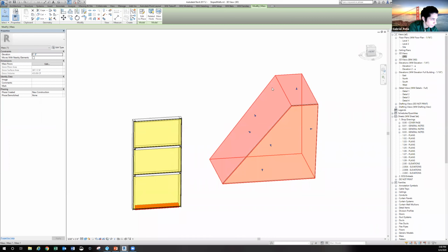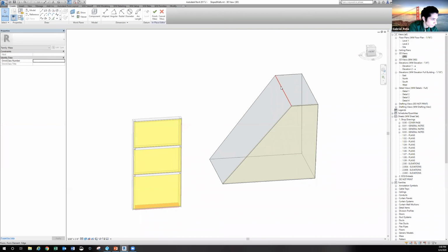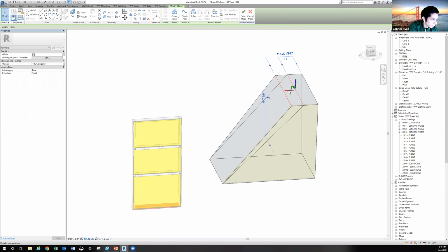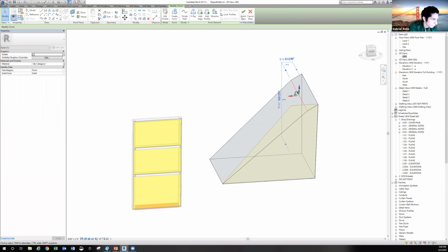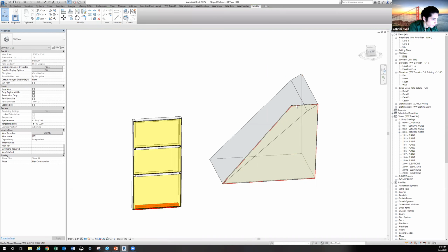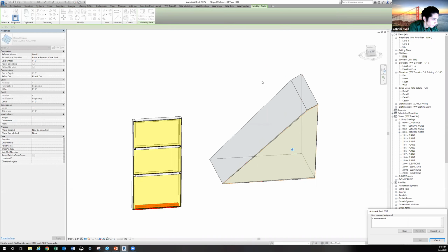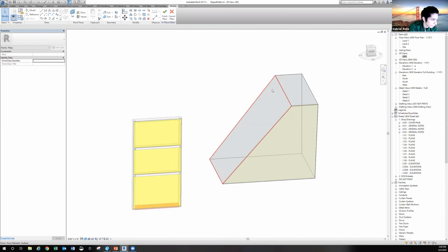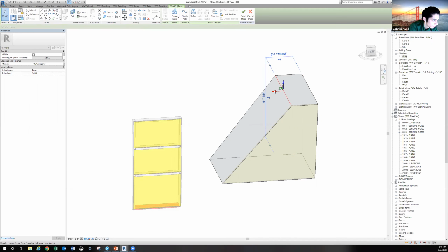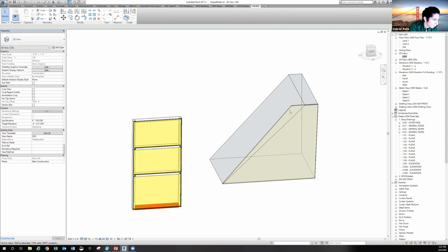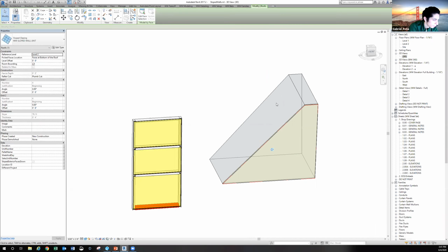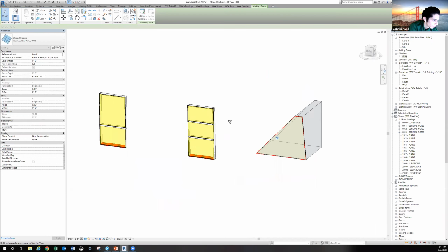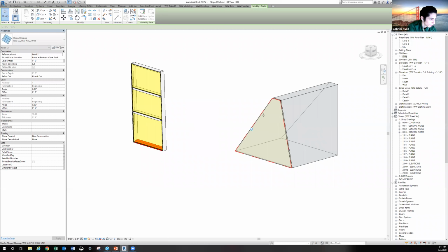And the good thing about this is if this gets adjusted for whatever reason, it gets smaller and gets moved down or whatever it is. Let's see if I just messed it up or not. Update to face. Yeah, I can't make that roof. I think that last thing I did messed it up. It just got smaller, and I update to face. We can do something like that and then just apply our mullions.